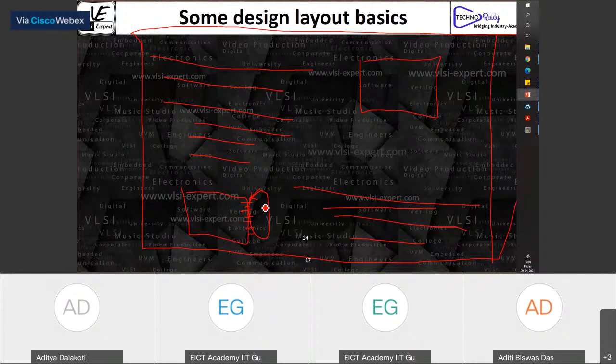Do I have 100 channels available for me to route here? If not, then it sees congestion. Similarly, in the vertical direction, it says there are 200 pins I have to route to this, and do I have 200 vertical tracks available to me or not? Otherwise, it sees congestion. That is how it tries to figure out whether it can route to a macro or not.